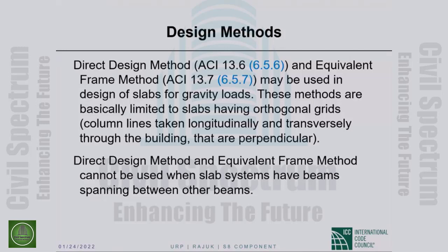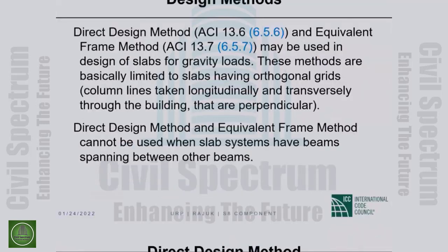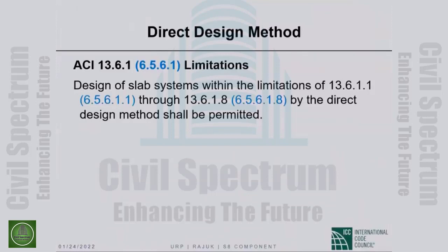The equivalent lateral force procedure is done on the computer. You cannot do it by hand, I do not believe. So I have restricted myself here to the direct design method because I want you to share that feel for what we are doing. I had 30-some slides on the equivalent lateral force procedure that I have removed from the slide set. We do not have time for that, otherwise I would have gone, and in any case it does not give you any feel. It is just prescriptions for the computer programs.